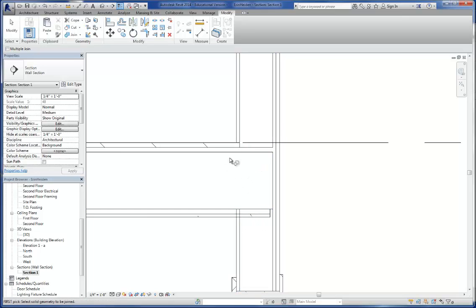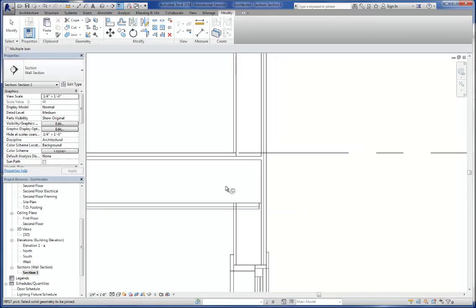And then the joist here is going to sit on top of that, and then there's going to be some plywood sheathing that sits on top of that, and then the structure for the next level is going to pick up from there. What you're going to see then is it looks like she had a hardwood floor set up on this, so this is a butt up against the structure, and then the gypsum board on the interior wall is going to come down on that.